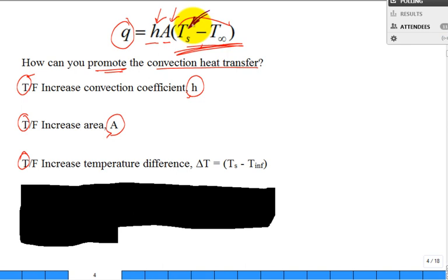They used to run them a little higher, like 210, 220, 230 in stock. Okay, degrees F, all of these. And then I would not recommend it, but they do sell some low thermostats, like 165, 160, somewhere in there. Mine never seemed to run well, either on the high or low. Just get the stock, the original. So you're kind of stuck with this one, right? You don't want it too hot.